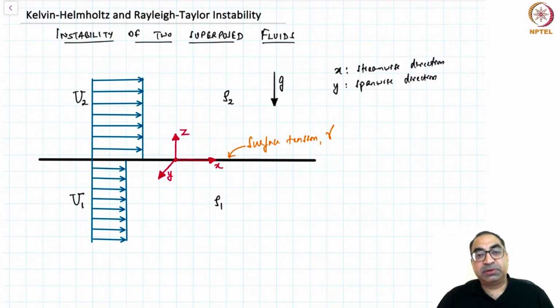In some of the stability problems that we've looked at in this course, such as the Rayleigh plateau instability, or the stability of a thin film, or the Marangoni instability, the base state was completely stationary. There was no velocity in the base state at all. We will now be looking at a problem where the base state has a velocity, and this velocity is actually changing in space. The way we set up the base state is to merge two streams with different densities traveling at different velocities to basically come and meet at an interface.